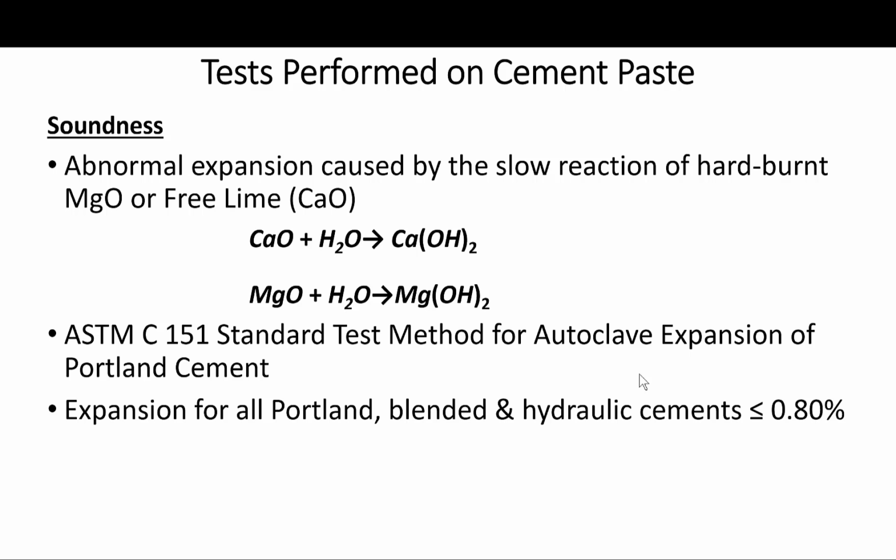We are going to talk about the tests performed on cement pastes now. Let's talk about the unsoundness. Unsoundness in cement paste results from excessive volume change after setting. If there is any appreciable expansion, however slow, cracking and failure of the concrete will result.